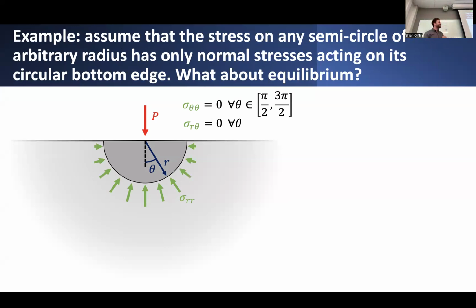How far away? Well, that's precisely the subject that I hope to conclude on today. But to cut to the chase, there's this thing that maybe you've heard of called Saint Venant's principle, which basically says that you can replace some load, and this is a good opportunity to explain exactly how we are going about this solution. We can replace some load, it doesn't matter how it's represented. In this case, assume that the load is represented as a point load.